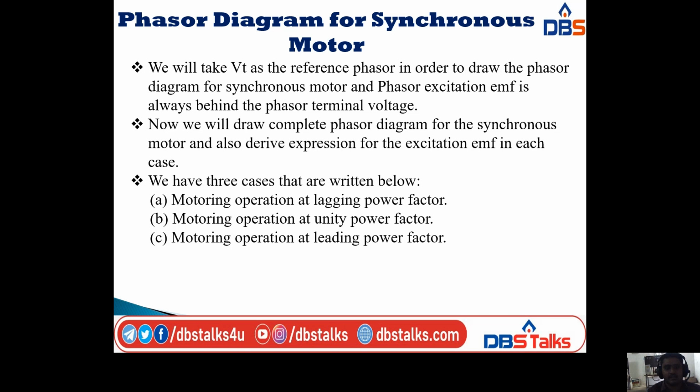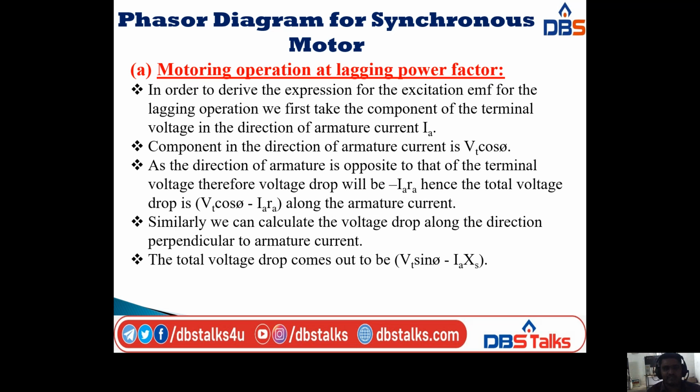Now we will draw the complete phasor diagram for the synchronous motor and also derive the expression for the excitation EMF in each case. For that we have three cases: first, motoring operation at lagging power factor; second, motoring operation at unity power factor; and third, motoring operation at leading power factor. Firstly I will take the first case, motoring operation at lagging power factor.